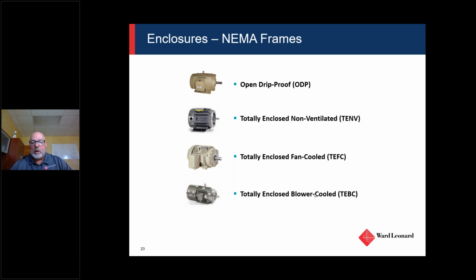Then a totally enclosed blower cooled motor would be a good application if you're running a VFD where the motor could potentially run slower and doesn't have the ability to cool itself, so we'll add an external blower, right? The external blower just runs at a constant speed, so it keeps the motor cool. So if you have a VFD application and you keep losing motors because they are running hot, then we may want to add a blower to it.